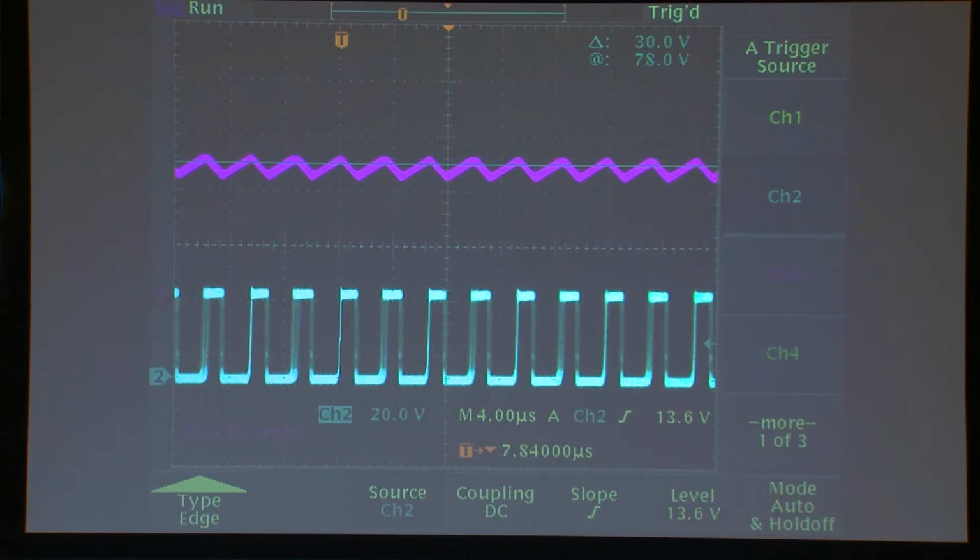And that's pretty nice, right? I got more or less periodic steady state operation. There's actually a tiny bit of jitter in the duty ratio here, but it's basically switching once per cycle and nicely settled down. What happens if I turn off the compensating ramp?